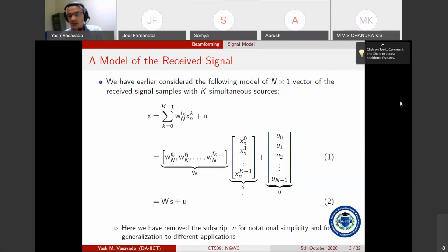So for QPSK, it is like 8 possibilities. QPSK is only 4. I mean, like 2 users and QPSK. So at one time, I will get QPSK symbols, 4 of them from one user. The other will be zeros. Why will others be zeros? When one user is transmitting x0, can that user say to user 2 that you transmit 0? The first user cannot say that.